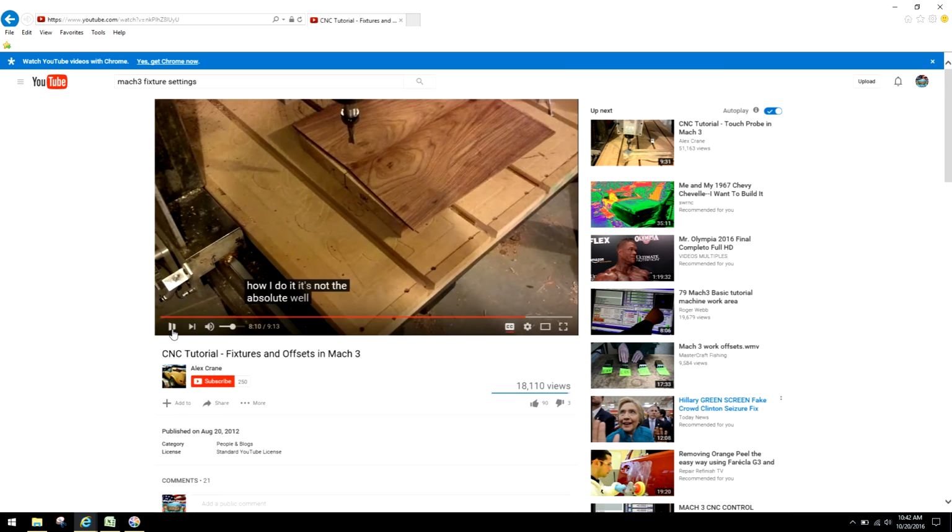It's not the absolute. Now guys, when he says I'm going to do the Z in the next video, Z is very simple. Depending upon tool changes, once the Z is set, and it's set basically the same way, it's all digital coordinates. The software is just recording the position you are setting. Pending this material is the same width, and you leave a couple thousandths variance for using the same tool. If you're doing roughing, of course, you're going to be using the same tool. So on that process, you would do all of the same material that you're roughing with, and then change out your end mill.